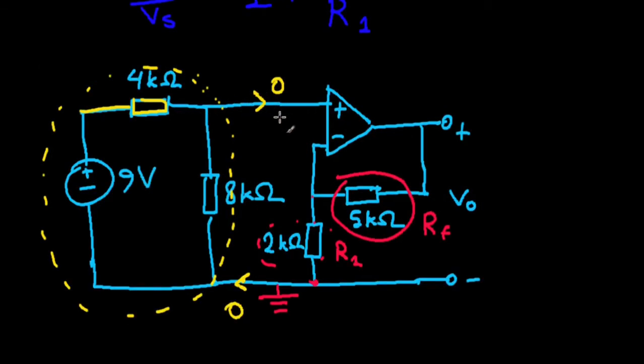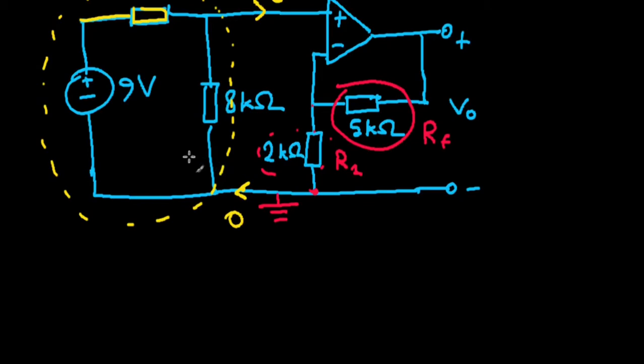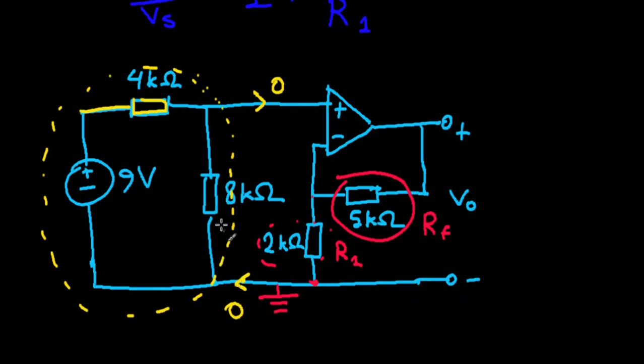If you have just one path for the current to flow, it's actually not going to flow, because a closed network cannot gain or lose any current, according to KCL. So the current here also has to be 0, like this one. Well, if both of these currents are 0, this loop is just operating by itself, an independent loop.